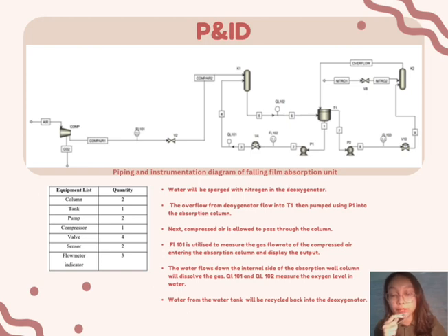They are purposely placed behind the valve to avoid any velocity profile disturbance that might be caused by the valve. Components labeled QL101 and QL102 are oxygen sensors that measure the oxygen level in the water.